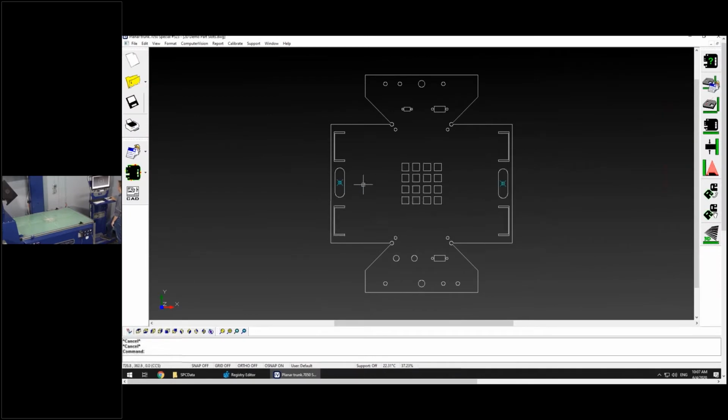collection points. As I discussed in the update email that I sent out to you guys for the webinar, we can now do collection points automatically generated with a click of a button and get the XY locations from a datum. To make it easier for you, if you turn on collection of arcs and collection of rounds, it'll automatically put the center point in the center there. We can go into our inspection report manager, say automatically generate my XY location from my datum point, and we did every slot that's on the part in a matter of seconds.